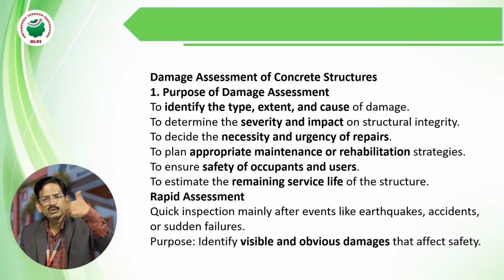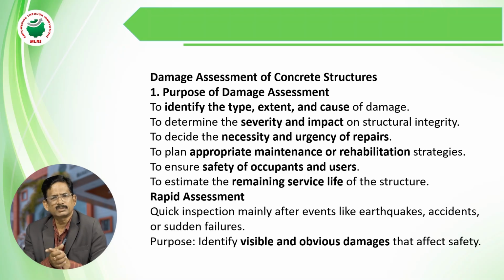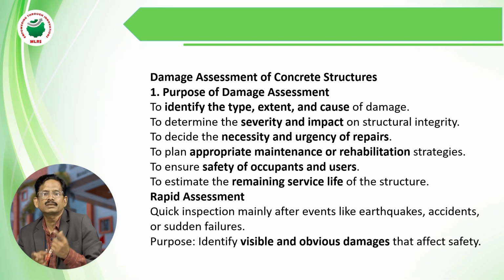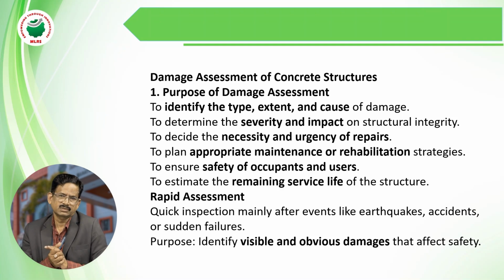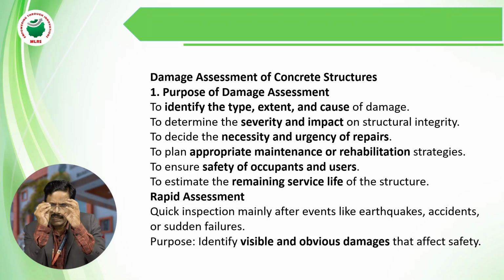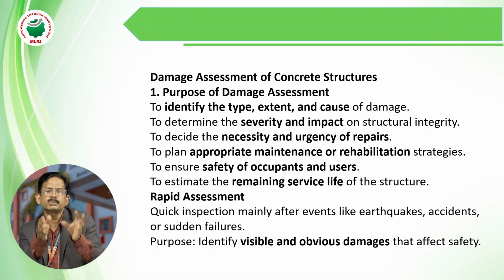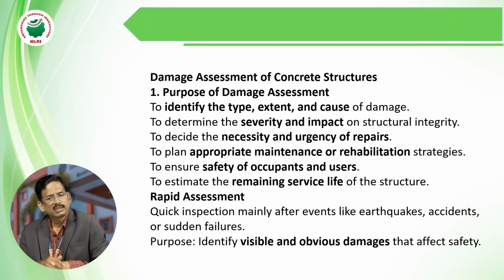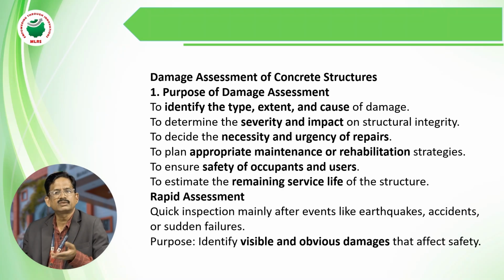Suppose you are doing the plastering and on the first day or the second day itself we see some short-term cracks. Those are not serious. But if you are seeing any cracks over the brick, that is very dangerous. So that's why we have to see the intensity of the crack, whether the crack is small or large. We already studied this in the design of RCC structures at the BTech level, and the code book also had it.